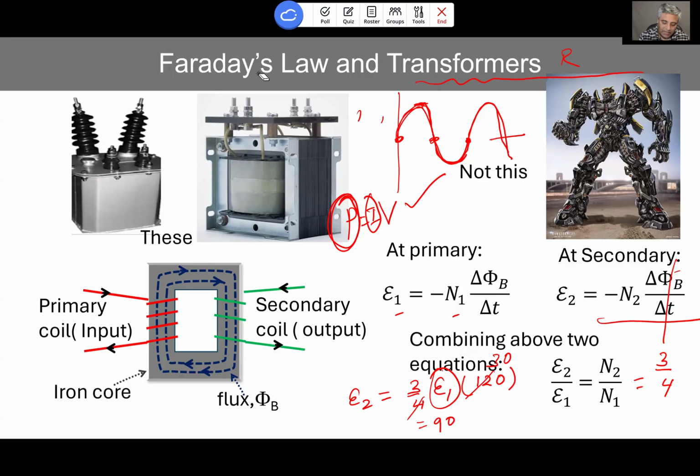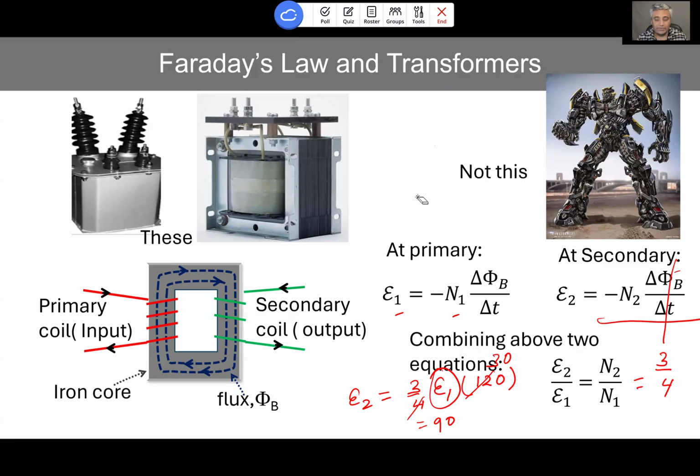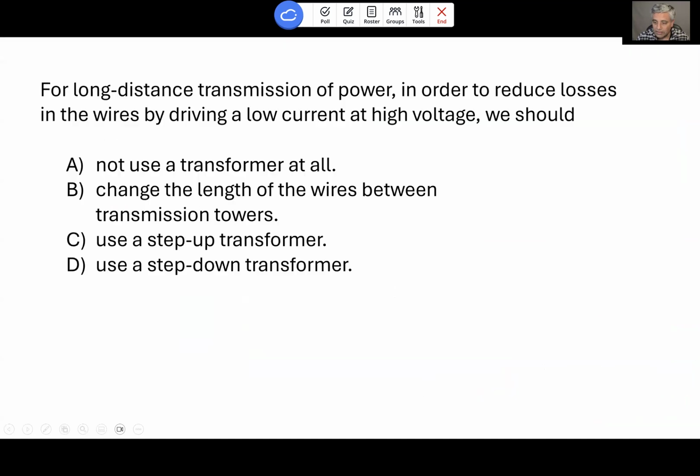We do not want to do that. So because of that, what we do is we use this transformer, this time a step up transformer. That means it brings the voltage from a low value to very high values. So if you see tall transmission lines around town, that means they carry thousands of volts. High voltage means current is small, and once current is small, the dissipated power in the wire becomes less. So that's why they transmit at high voltage. This is how a transformer works, and we can have step up and step down transformers. Hopefully now you fully understand that.